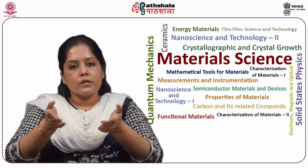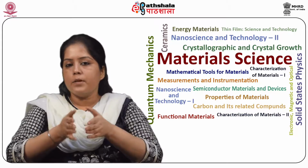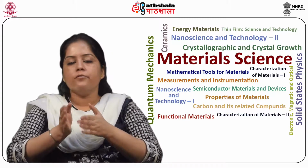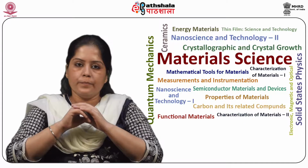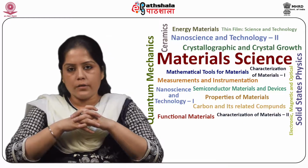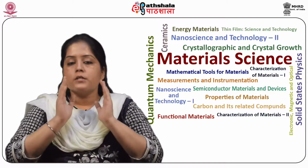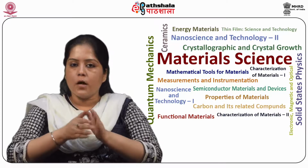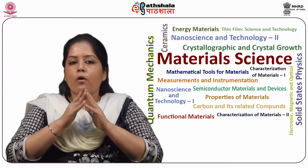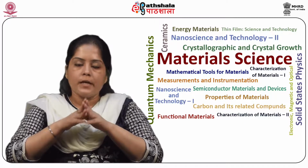The effect of microscopic properties is symbolized by G, R naught, F, and Q. For perovskite materials, it was observed that the electrostrictive coefficient is strongly dependent upon the level of the order-disorder of B-site cation arrangements.